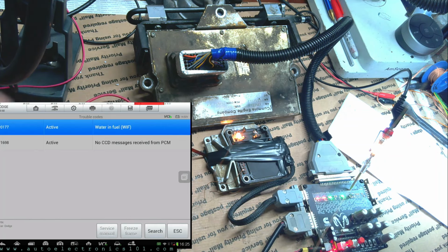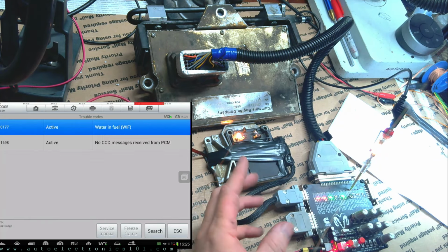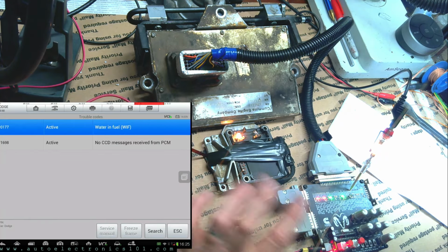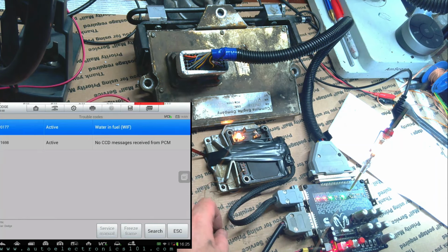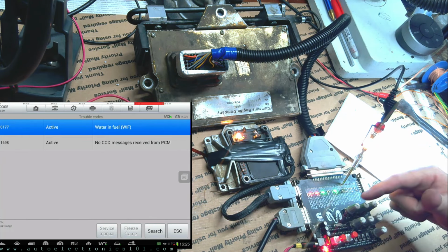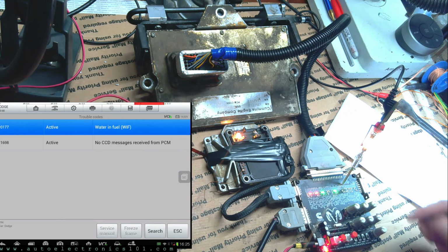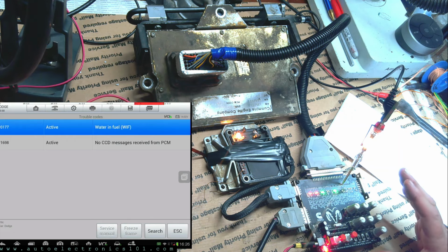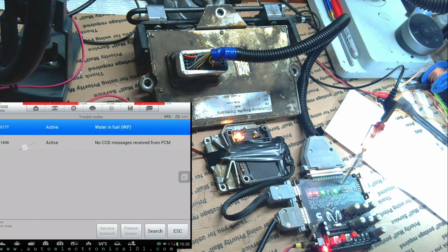I can't remember if this system will tell you if it's active or stored. They might only give you codes and not tell you if it's actually a current or history code, because the low voltage ones are very weird because I'm looking at my tester here and I know the ranges of where the pots are pretty much set at. And I know they're not low. Only the water and fuel is a weird one. The other ones are pretty good there. So that could have been external issues that just happened to still be there. So 1698, is that the code that? No, 1689 injector pump. Yeah.